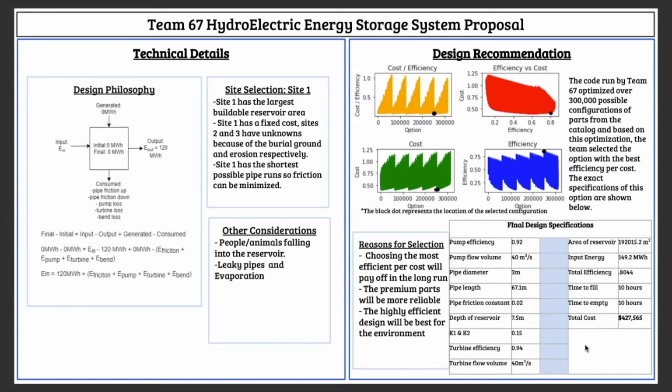After further considering the different potential building zones, our team also decided to not build on Zone 3 because of the concerns surrounding erosion in this location. Given that the reservoir would rest atop a hill in order to maximize energy storage, any erosion would have a profound influence on the integrity of the system. Shifting of the surface underneath the reservoir because of erosion would cause cracks in the walls and floors of the system, which would allow water to leak from the reservoir, leading to a decrease of efficiency.